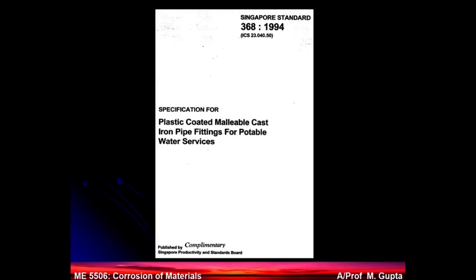Same thing for the pipe, cast iron pipe fittings. If you have a pipe like this and you have a special fitting here, which is thicker, for the steel you use a cast iron pipe fitting. Reason? Impingement corrosion. You need a much harder and stronger material because the turbulence is maximum in this area. So again, UPVC, you can use it.